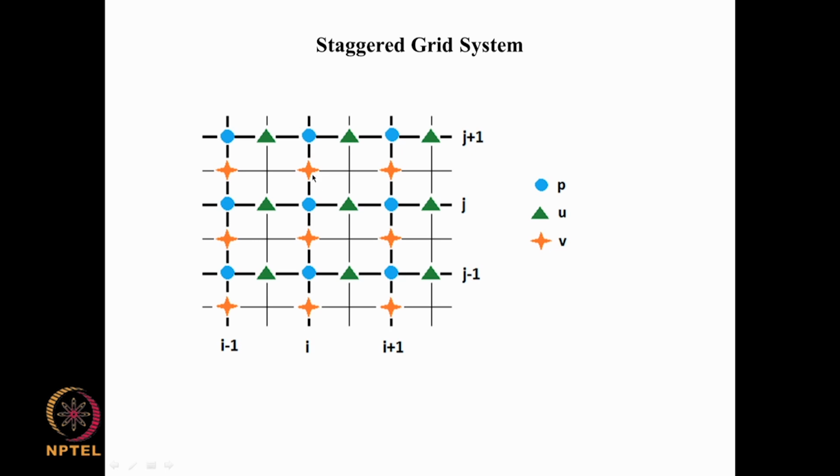So, in that sense, even if you had 100 10 100 and 50 10 50, you would not be getting the pressure gradient evaluated as 0 at the points where the momentum equation is being evaluated, and therefore, the velocity field will be responsive to these pressure changes here.